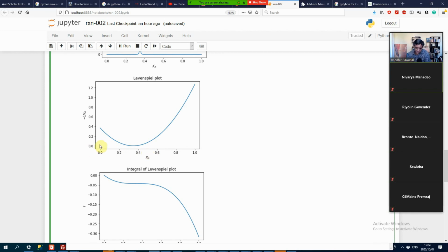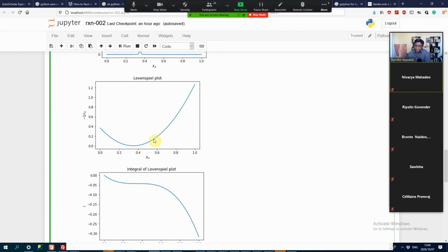So by putting the CSTR first, we've taken advantage of these kinetics and we've achieved a high reaction rate in that CSTR. By putting the CSTR second, we are now in a region where a high conversion translates to a low reaction rate.